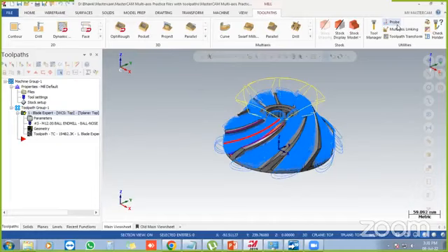So we can adjust that tool diameter in Mastercam and inform it that the standard diameter is 20, but due to wear, it has become 19.8. So it will cut that particular part accordingly. It will understand that the tool has worn out, so it will generate toolpaths with that clearance. So yes, that can be addressed in Mastercam.